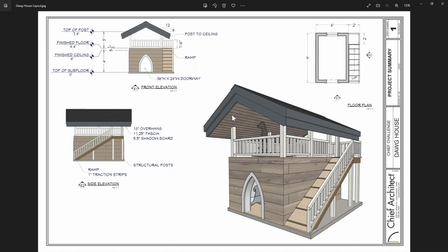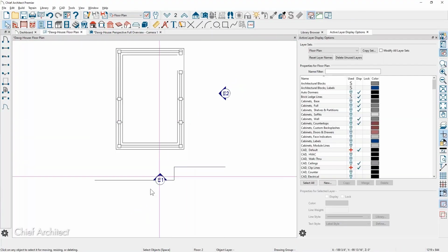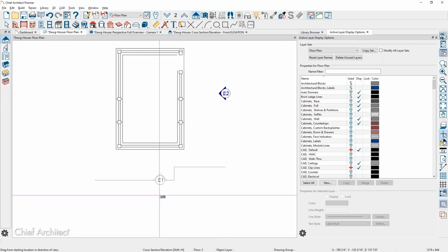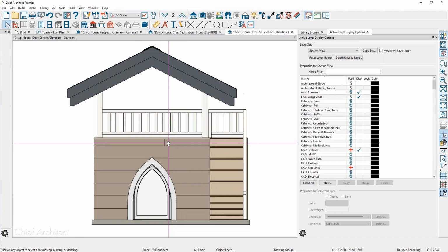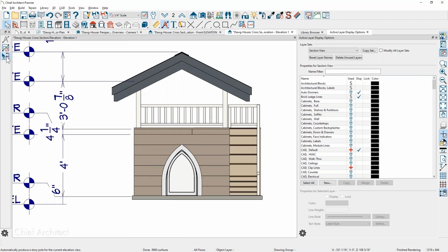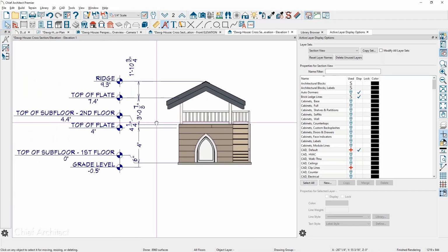And then once you place the dimensions, of course, you can completely customize it, which then I've done here in this example. If we go into an elevation view, and let's just open that up. So here's the elevation view that I've done. And if we open up a new elevation view, so let's just draw a new one here, and let's drag that in. So here we are looking at the elevation view. You can configure those settings. First of all, the automatic dimensions. I'm not sure what I have it configured now with this particular plan, but using the automatic dimension tool, the tool on the left-hand side of my monitor is called the auto story pole dimension. And that will then come in there and place all of those dimensions.